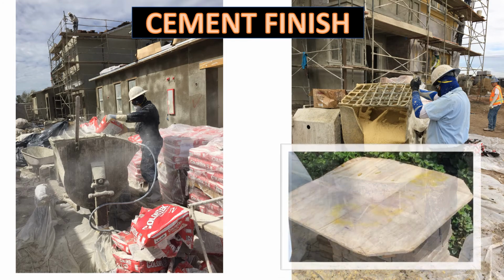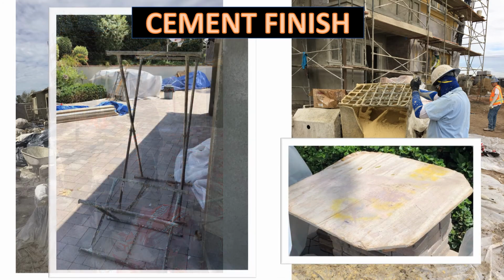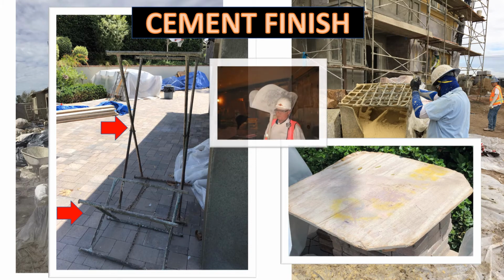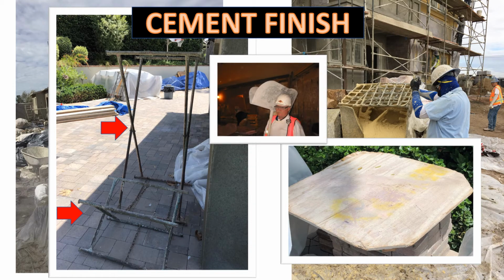The mix is typically placed on a mortar board or what we call mud board. The board is placed on a stand. Mud stands can be short or they can be tall. At one time, the hod was used to bring the cement mixed and dumped on a pre-wet mud board. This is where the term hod carrier came from.